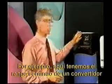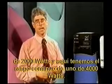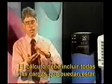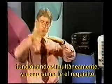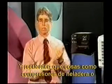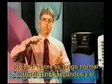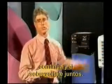For example, here we have a 2,000 watt inverter. Here we have a 4,000 watt inverter. Continuous rating. You've also got to choose an inverter that can surge enough to start your motor loads that might come on. The calculation should include all of the loads that might be on at one time, and then add to that the surge requirement of the heavy motor loads. And keep in mind that things like compressors on refrigerators or motors for water pumps can surge 5 to 6 times their normal rating for a few seconds. And the inverter must be sized to not only handle the continuous load, but supply that surge as well.